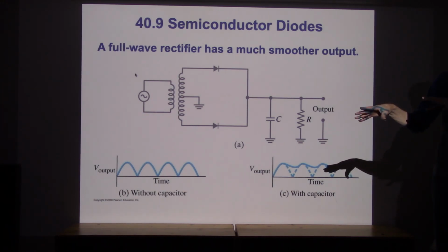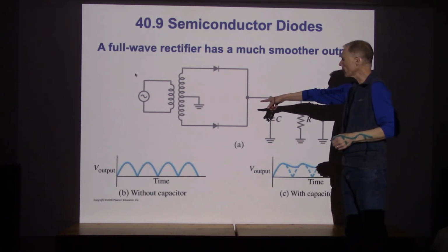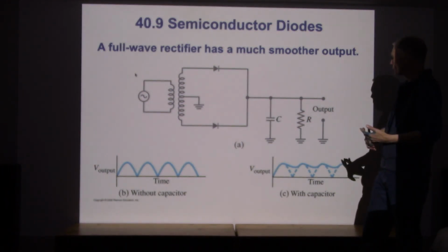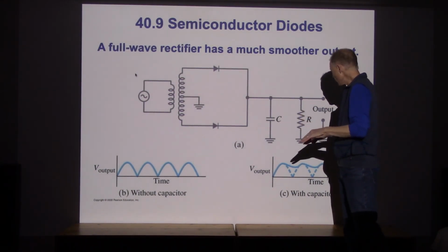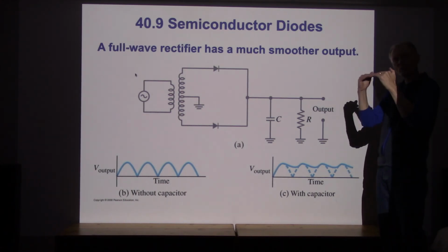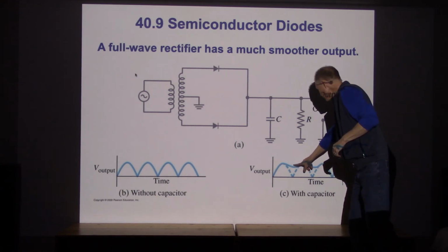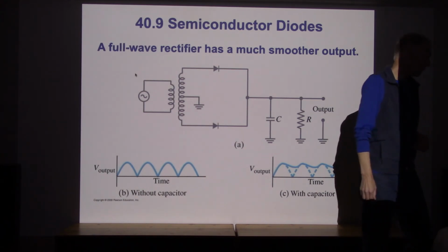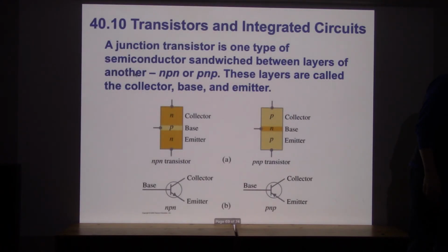If we have an AC source, but we want a DC power supply, we can take a transformer, run it through a rectifier, which is some number of diodes, and this is not the only possible configuration. And then we can use some big capacitors, relatively big, to smooth out that effect. And then you can get to where you have a pretty smooth output, right? Some bigger capacitors here, and maybe we've got a pretty flat line in terms of the voltage output. So diodes are really handy. Diodes show up in converters.